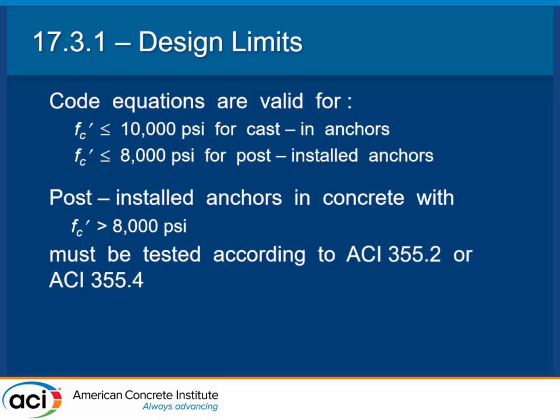Post-installed, I don't even know what you have. We did try for a while to give some basic information so you can get a preliminary analysis done using post-installed anchors. That's largely gone away. Really, you just have to use what the manufacturer's testing gives you, and they might have something that goes above 8,000 PSI. As long as they've run the protocols and made the sheet, then you're good to go.